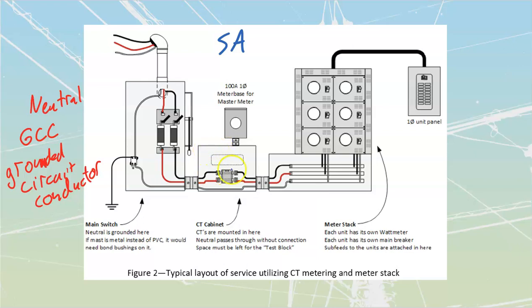There does also have to be a chunk of space that's going to be left inside of here. One of the big errors that most electricians make on their first service that has one of these is they're going to mount that CT right in the middle of the box, because you get this big old box and you get the CTs, you get big conductors, and they go perfect. I will shove that thing right here into the very center of it. That is always going to be a mistake because there's going to be, think about roughly like a shoebox size device that has to go into there.